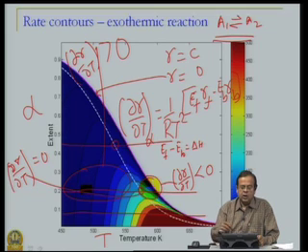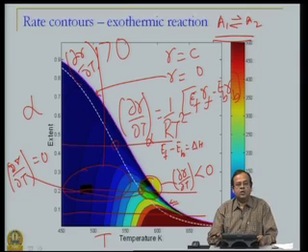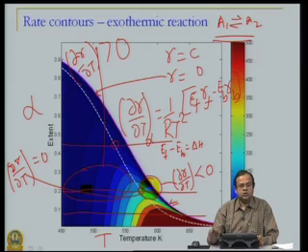As a result, after a certain increase in temperature, the thermodynamic constraints come into the picture, because now the equilibrium extent of reaction is limited when temperatures are high, and therefore, the rate starts decreasing and eventually reaching a 0 value, that is this equilibrium line. So, this is the conflict between kinetics and thermodynamics, which is represented in this contour plot.